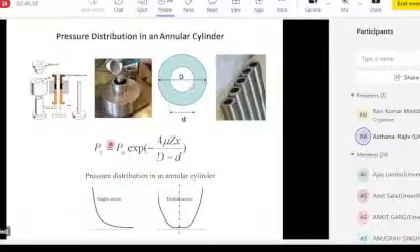So if you go through the analysis, you will get the same kind of exponential form for tubular components also. But you will have a wall thickness term coming into the picture here. So these kinds of simple analysis allow us to capture the effect of parameters like size of the die, distance, friction coefficient, and the applied pressure.